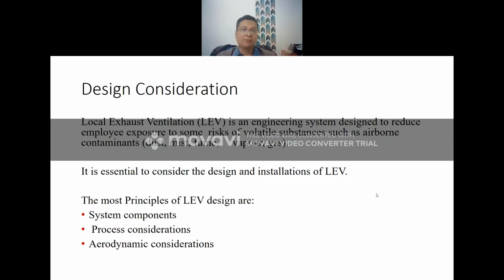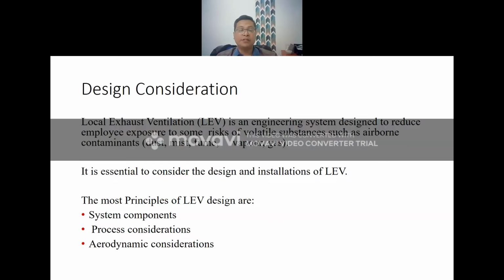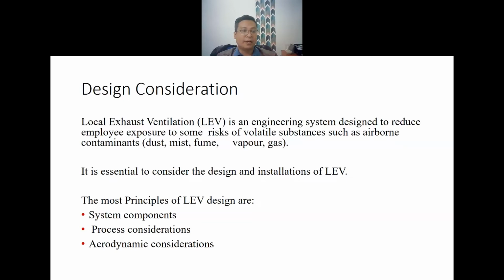These are part of the parameters to consider in the construction of the LEV itself. Actually, it's not only about throwing out the hazard; we need to filter first. We also need to design the exhaust system for aerodynamic considerations, because we try to attach it to the building architecture.